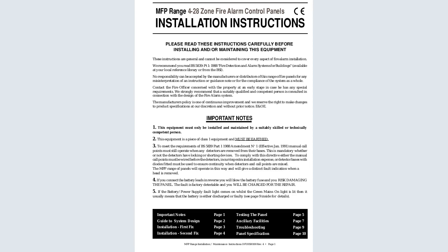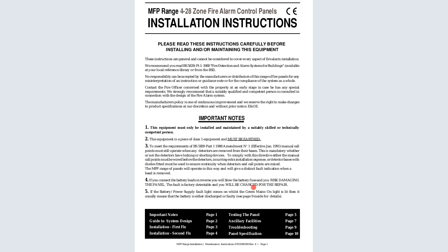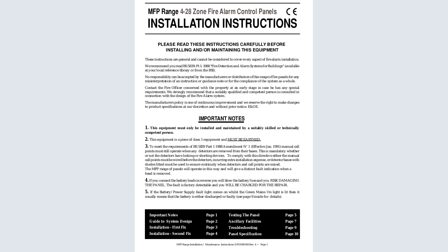To meet the requirements of the BS standards, a manual call point must still operate when any detectors are removed from their bases. This is mandatory whether or not the detectors have locking or shorting devices.